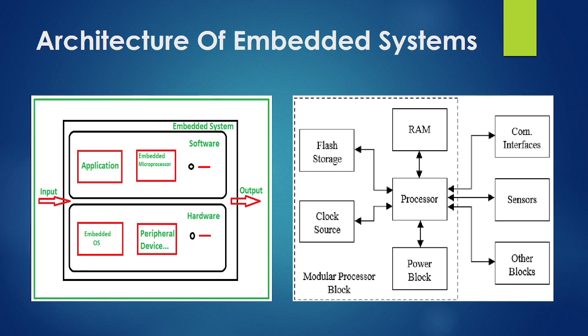It could be we are connecting VCC to the 5 volt, ground to the ground pin, and then at one pin we are connecting it to the digital pin. So this is simply interfacing, but it will not work just by interfacing. We need to insert some code inside it for it to work. For inserting that code, we write the code in the integrated development environment, and we insert that code into the microcontroller board, and then it gives an output.